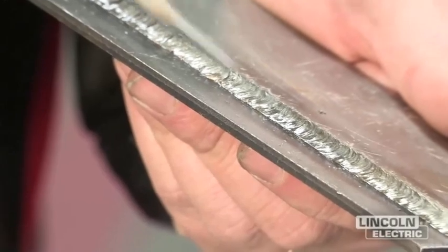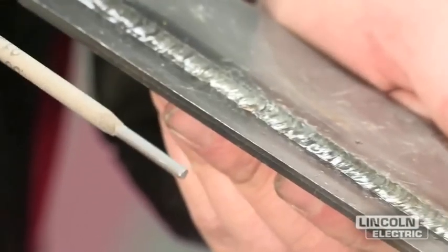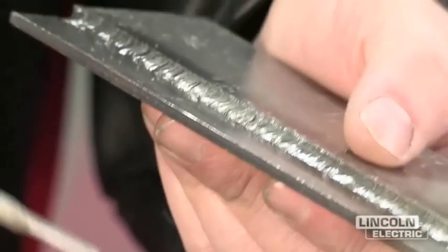So as a summary, just to wrap up what we've talked about, there's four general areas that we can focus on for visually inspecting a weld. One of them would be a flat face. One of them would be proper placement in the joint. One is fairly uniform, being the weld consistently shaped down the joint. And the last one is good wash-in at the toes of the weld.